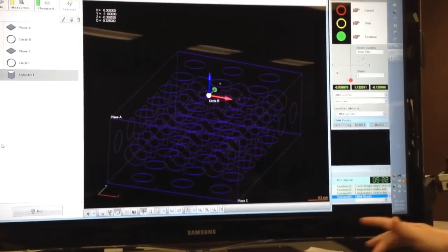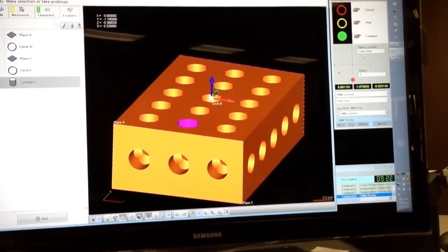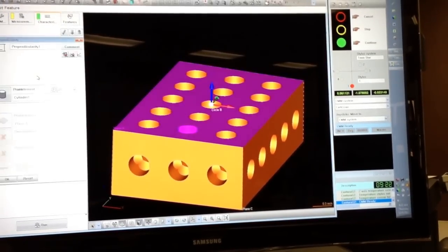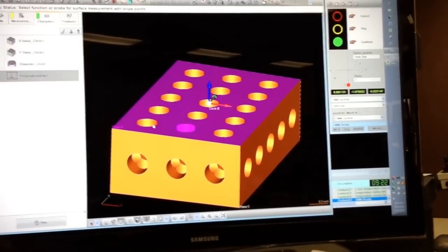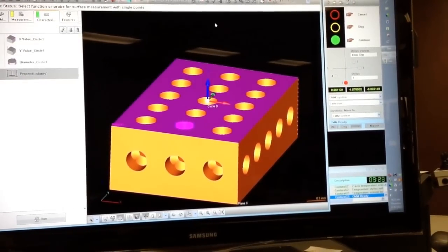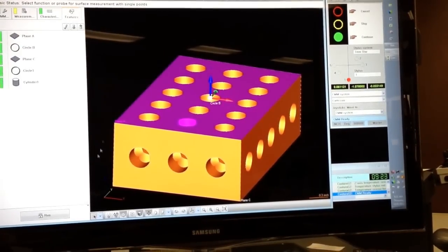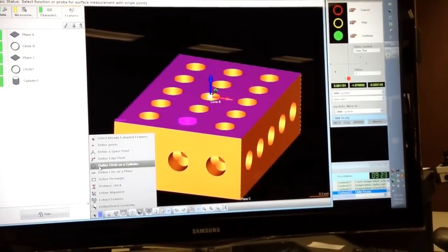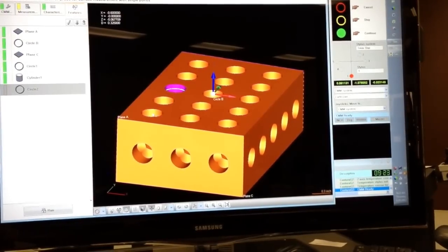Once again, I will use an F9 to test this feature. There it goes. And if I wanted to double check the characteristic, I have some results now. Next, the 2 Cartesian distances, hole-to-hole distances, using the 3 holes along the left side. I'm once again going to switch my CAD programming tool to define a circle on a cylinder and get the next 2 holes that I need along the left side.